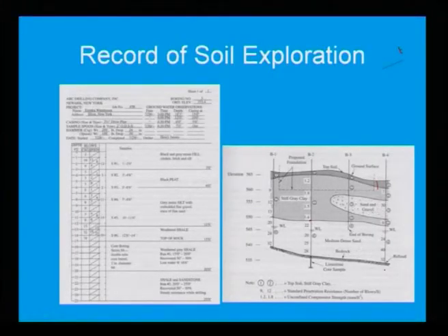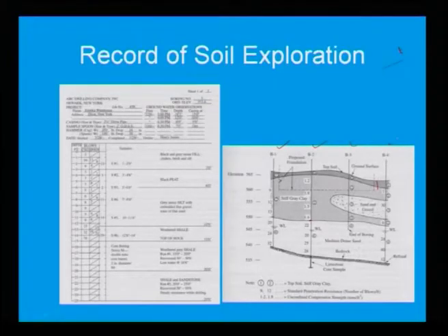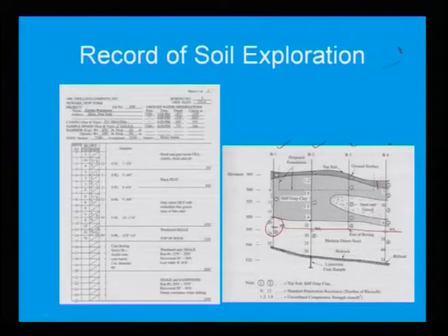Also the water table, is the water table varying from borehole 1, 2, 3, 4? If you look at here, the water table is absolutely not varying, it maintains constant depth, that means it is fine. Water table is not fluctuating. Your conclusion is the water table is not fluctuating. Sometimes, what happens is the water table is somewhere else, because of the soil profile.